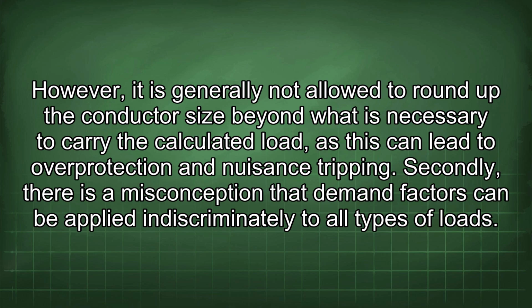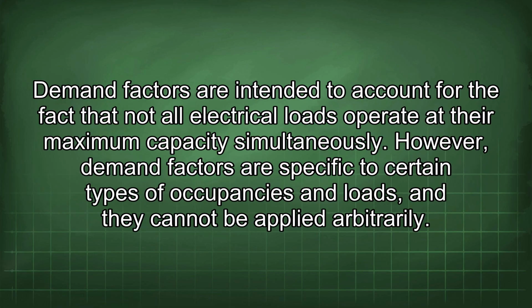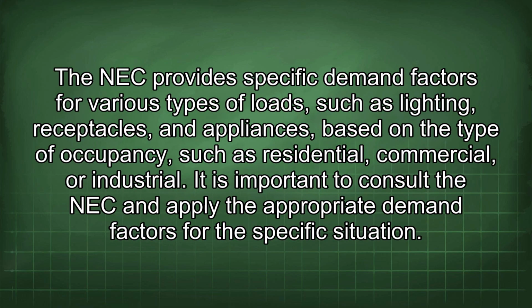Secondly, there is a misconception that demand factors can be applied indiscriminately to all types of loads. Demand factors are intended to account for the fact that not all electrical loads operate at their maximum capacity simultaneously. However, demand factors are specific to certain types of occupancies and loads, and they cannot be applied arbitrarily. The NEC provides specific demand factors for various types of loads such as lighting, receptacles, and appliances, based on the type of occupancy such as residential, commercial, or industrial. It is important to consult the NEC and apply the appropriate demand factors for the specific situation.